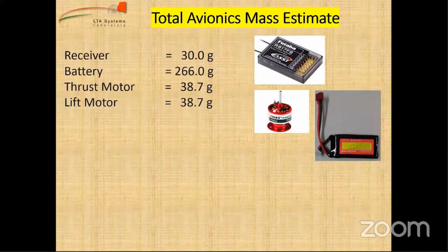Right. So does that mean the lift motor would not require that much thrust? It would not produce that much thrust, right? Sir, that will depend on the direction and the mass. Right. But in general, we can say that the lift motor requirement would certainly be less than the thrust motor. So that is how we could have saved a little weight by putting a lighter motor there.